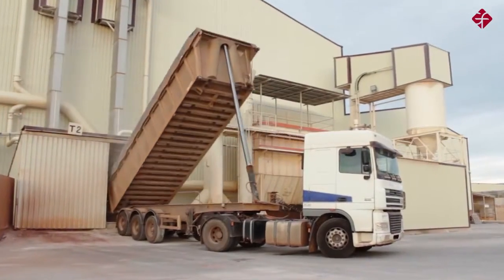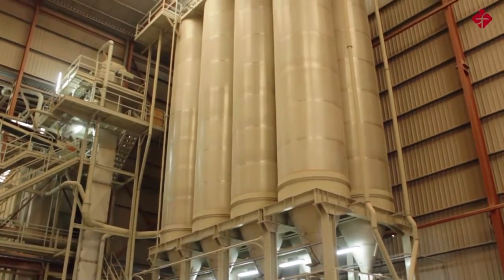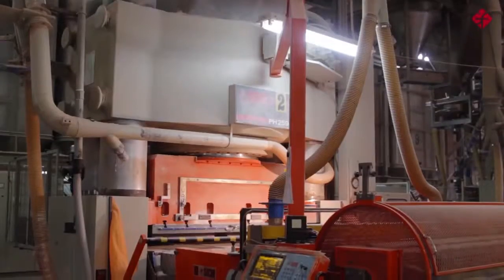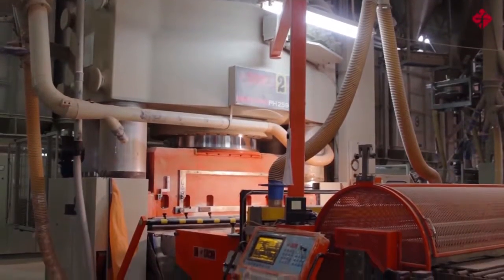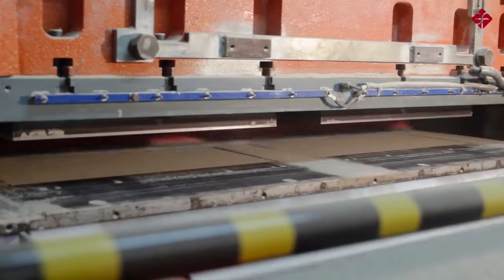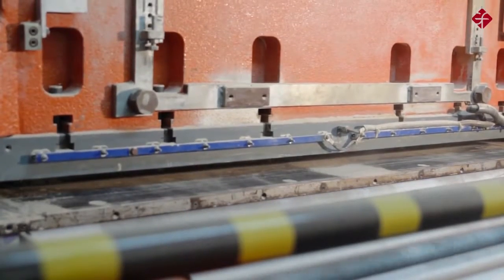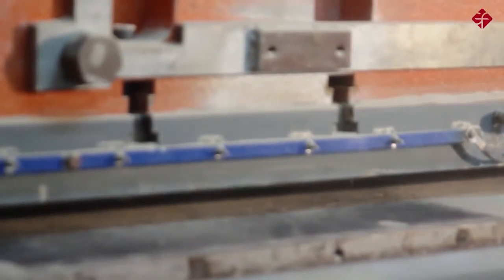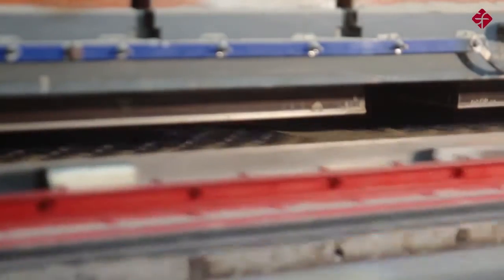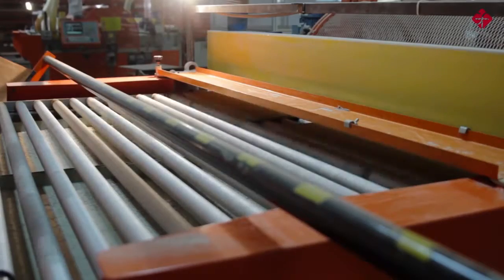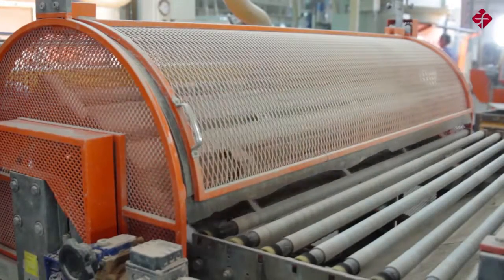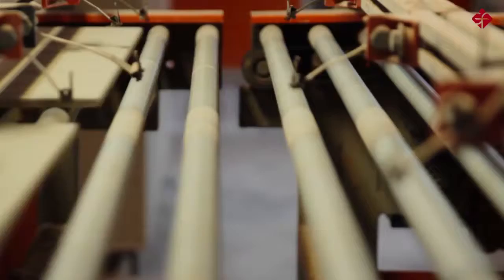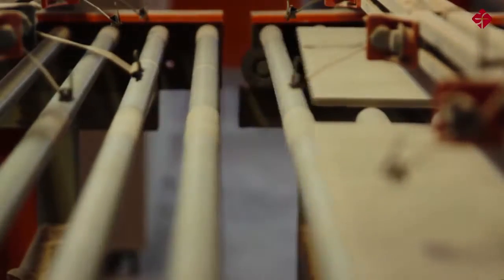The atomized dust is loaded into a silo and then fed into the cart on the press. These presses are one way, that is, they press in a vertical direction at high pressure to compact the atomized clay. The granules are literally broken, so the original particles obtained during the milling process, which would be the agglomerate, reappear. They start to stick to each other from the action of the press and their water content, which acts as a fluidificant, forming the raw tile with sufficient consistency to be transported.